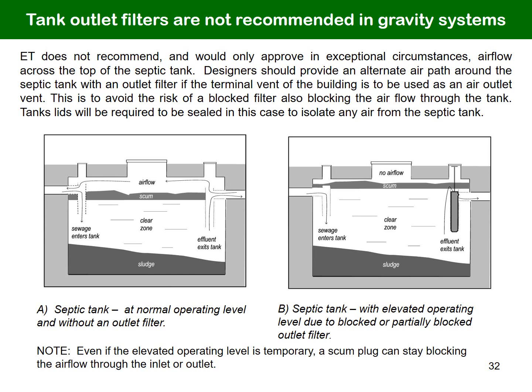If you are required to fit a filter, examine these two drawings. A is a septic tank at normal operating level and without an outlet filter. B shows a septic tank with elevated operating level due to blocked or partially blocked outlet filter. Even if the elevated operating level in the tank is temporary, a proportion of the scum or crust can remain blocking the airflow through either the inlet or outlet when the tank level drops.